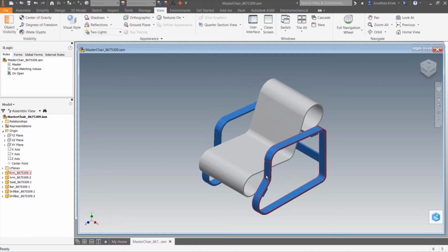So that's where we're talking about the strength of this, is that we can quickly go out and grab those components. We don't have to have them pre-assembled because we're assembling them on the fly using constraints and the Inventor API. And then further down, the last part is actually manipulating parameters if need be. So maybe I don't have 4 different parts necessarily for this component. Maybe I just want to manipulate the parameters for that.